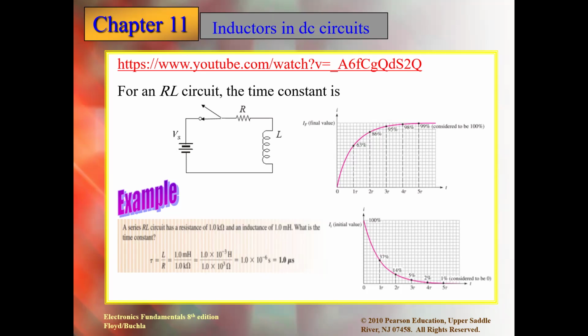All right. So here we have an LR circuit, which you can also call an RL circuit, and we'll be discussing the time constant here. The time constant which we have seen for the capacitor, we have a similar time constant here. For the capacitor it was tau is equal to R into C. But here tau is equal to L over R. This is the time constant. Here the inductor stores the energy in the form of, we can say, current, like the capacitor stores it in the form of voltage. In general, we can say it is stored in the form of current.